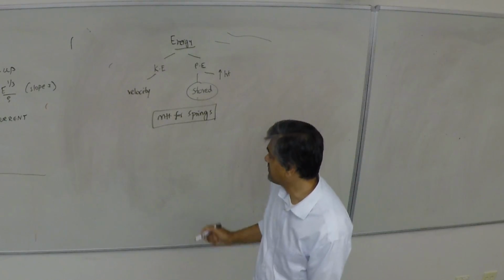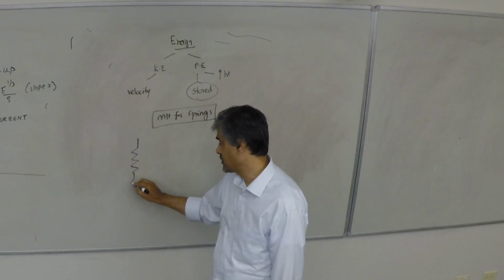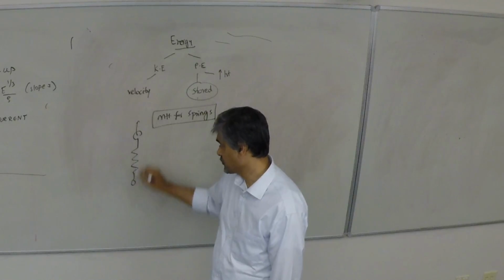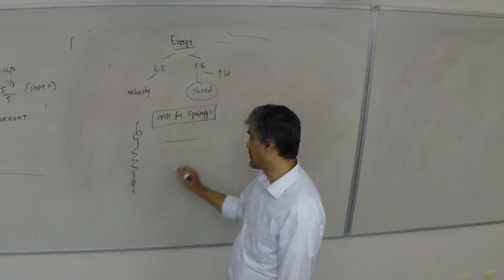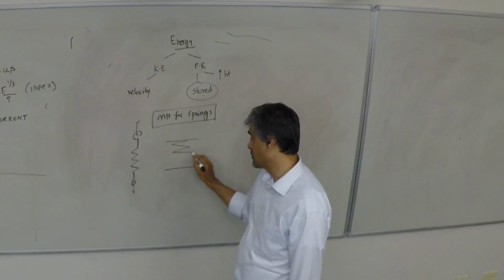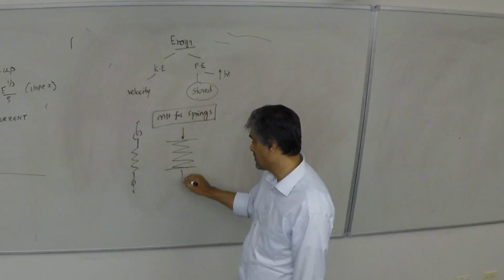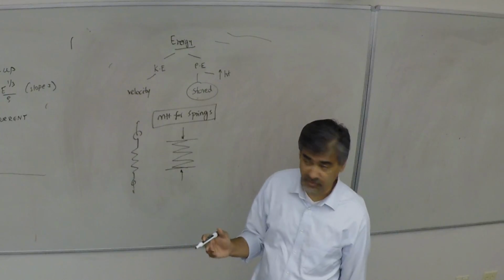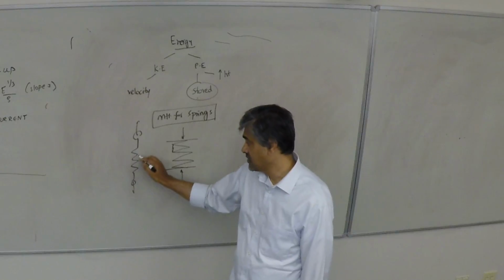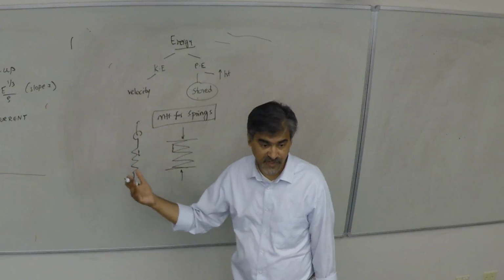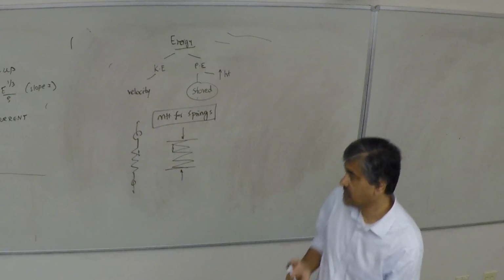And as you know, springs come in different flavors. Springs come as tension springs, where you're just pulling and storing energy in tension. There are also springs like in your trucks, machine foundations, and earthquake-resistant buildings, where the springs are compression springs. So there's a limiting deflection. When these things close off, the spring has failed. When a certain delta is exceeded, the spring has failed. It doesn't have to fail as in fracture; when it exceeds that deflection, it has actually failed.